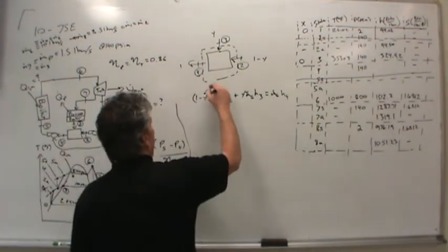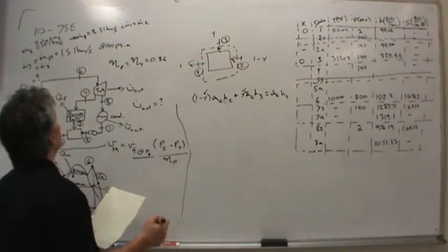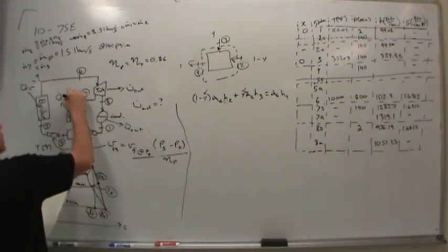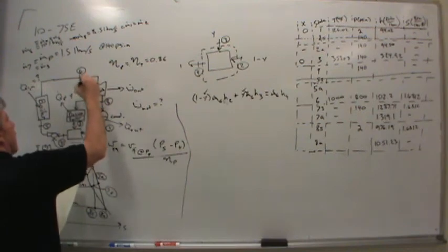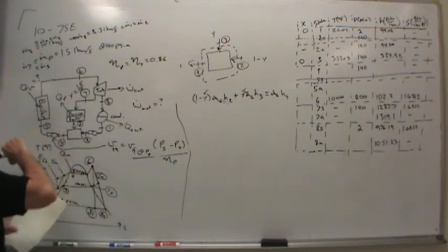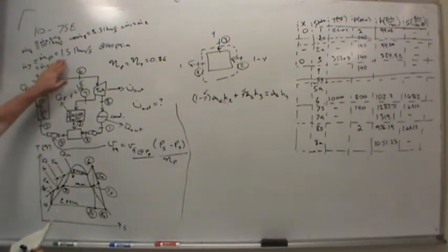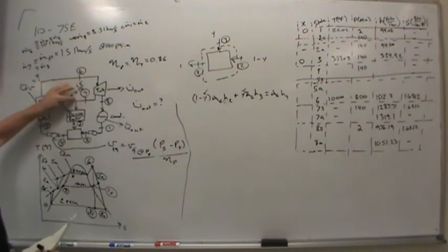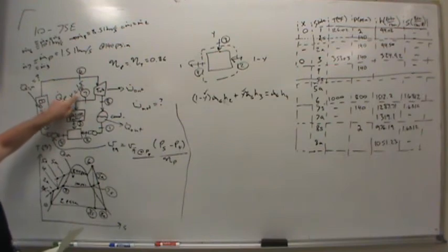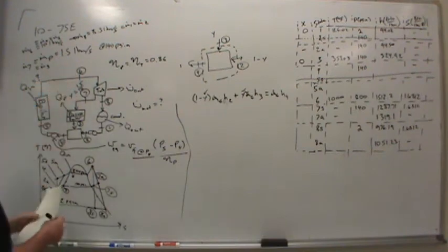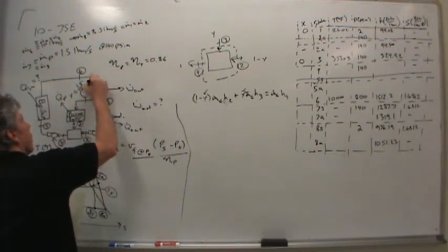And since we know the mass fraction, well, do we? Sure. The mass fraction y is simply 1.5 divided by 10. Why is it that? Because 1.5 pounds mass per second goes this way. Why wouldn't we divide that by the 8.5 that goes this way? It's because the reference for this mass fraction is always the flow through the boiler, which is the total flow. So this will come out simply to 0.15.